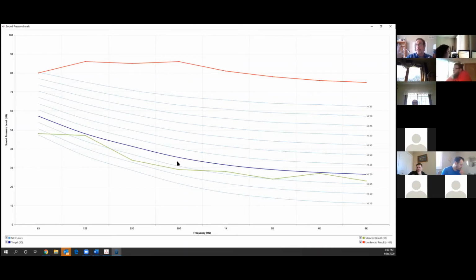I know in this model, York is really loud, and this model Train's really good, and vice versa. And then you get into custom stuff, it gets tricky. So as you're doing acoustic predictive, you may want to leave yourself a couple extra dB if you can, and cough up some pressure drop to accommodate it.